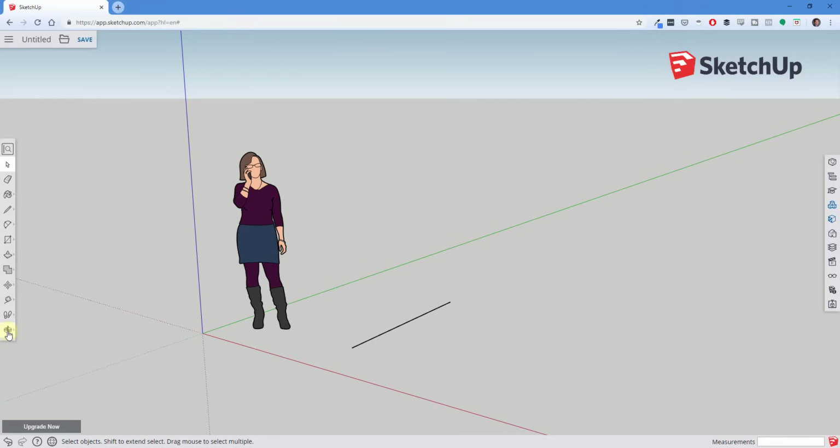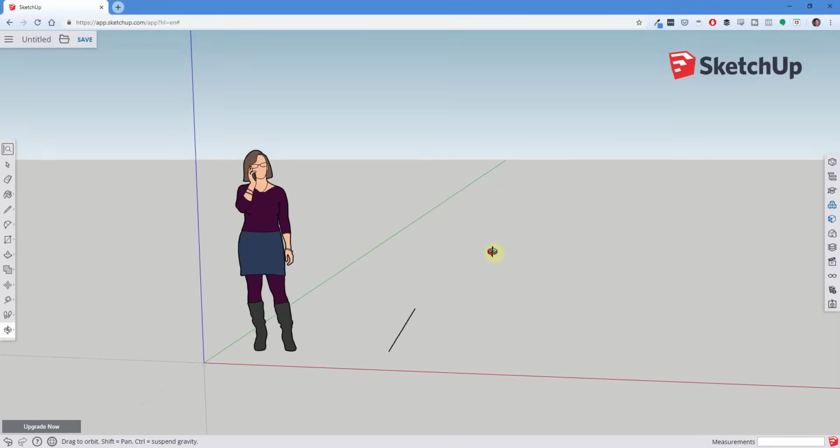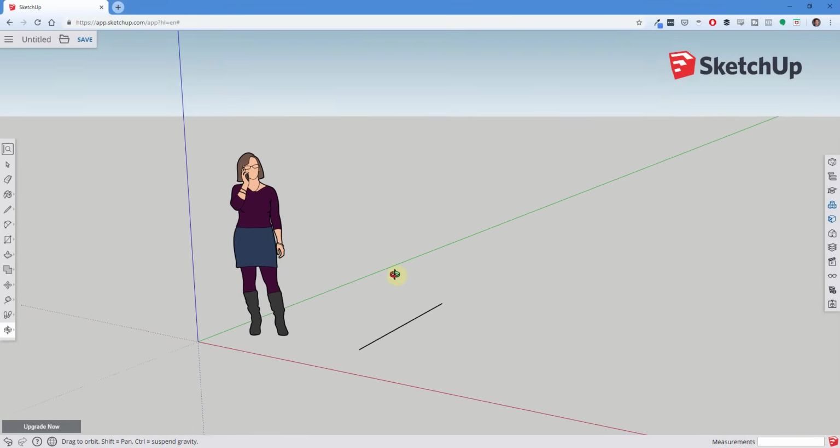The first is just to come over here and click on either these first person tools or the orbit tool right here. And you can see how there's multiple tools in here for adjusting your view and flying around with your camera in order to get to wherever you want to go inside of the 3D model. For example, the first tool, and the tool you're probably going to use the most, is called the orbit tool. And so you can access that by clicking on this button right here and clicking on the orbit tool. You can see how when you do that, you can then click and drag your left mouse button in order to fly around and orbit around.